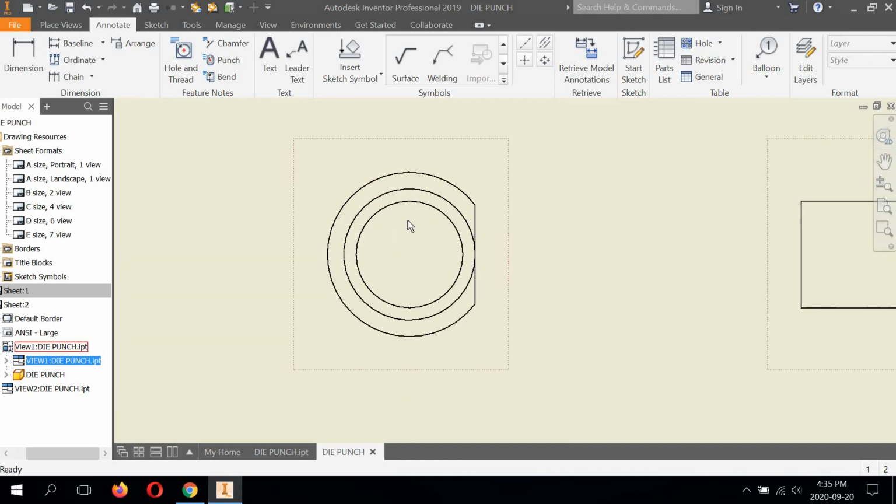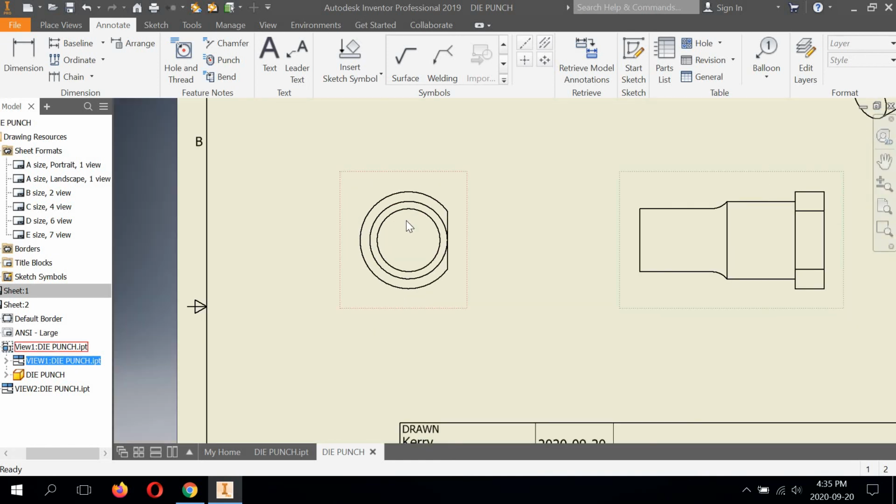So it's drafting standard in mechanical design. Anything that is circular or a circle and anything symmetrical requires a center line. Now there is a flat spot milled on the right side of this, so this is more a radius, not a full diameter.